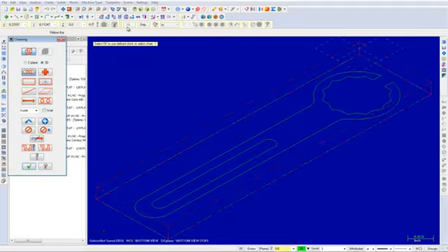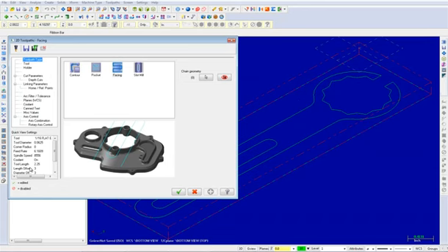When the chaining dialog box appears, choose the OK button to use Define Stock and exit the chaining dialog box. From the Toolpath Type page, the facing icon will automatically be selected. We will now choose a 2-inch face mill from the library and set the tool parameters. From the Tree View list, select Tool.